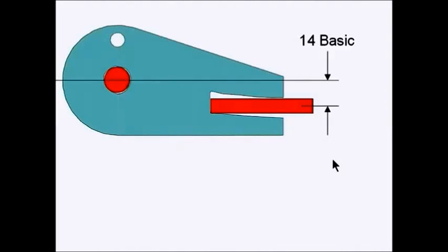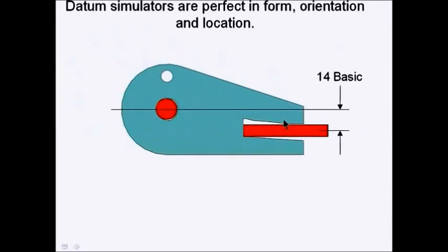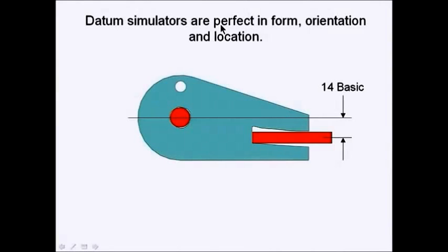The correct answer? Locate parallel planes at the basic location and expand them to fill the slot, because datum simulators are perfect in form, orientation, and location.